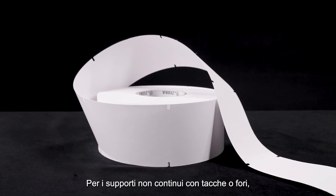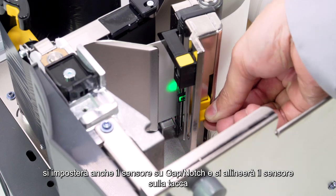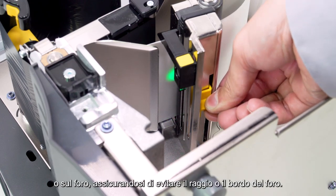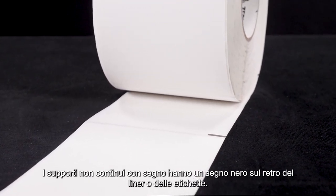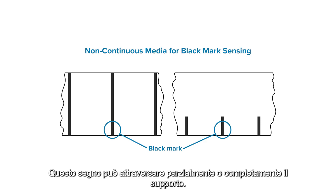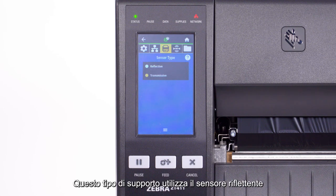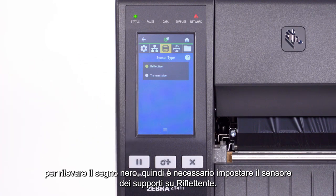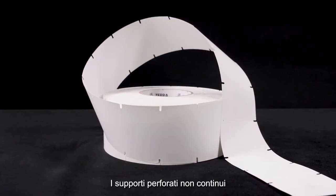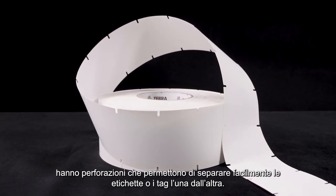For non-continuous notched or hole media, you will also set the sensor to gap notch and align the sensor over the notch or hole, making sure to avoid the radius or edge of the hole. Non-continuous mark media has a black mark on the back of the liner or labels. This mark can go part way or all the way across the media. This type of media uses the reflective sensor to sense the black mark, so you must set your media sensor to reflective.